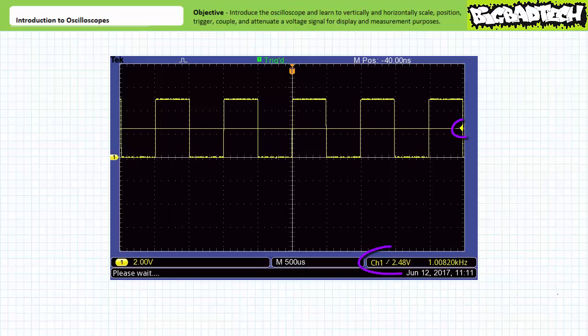For example, if we triggered not at 1.2 volts going positive, but rather 2.48 volts going positive, this just means the oscilloscope uses 2.48 volts and rising as our 1 beat. To adjust the trigger level, one uses the triggering knob. When adjusting the triggering level, you'll see the level rise or fall. As previously, every time the scope hits the 1 beat, in this case 2.48 volts, the oscilloscope captures a window of data and displays it on the screen. Really nothing has changed, only the repetitive waveform is being sampled at a different moment, thus shifting our capture window ever so slightly.